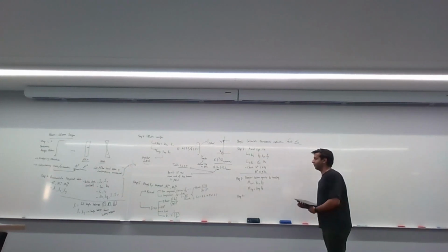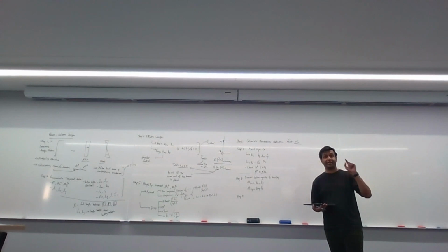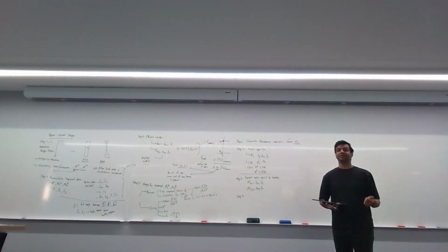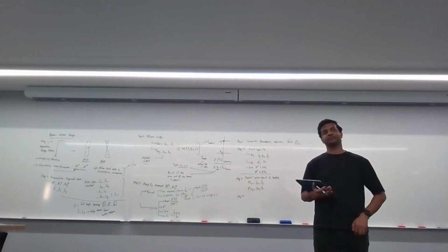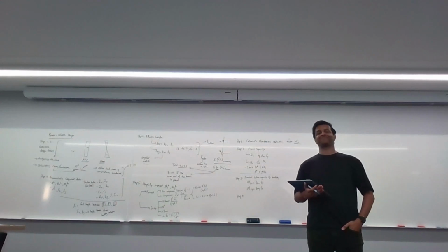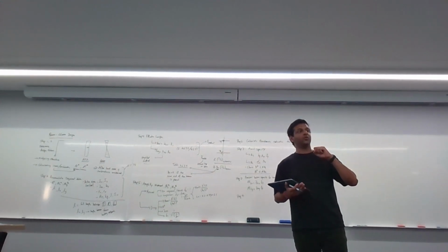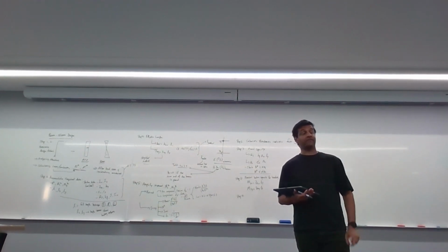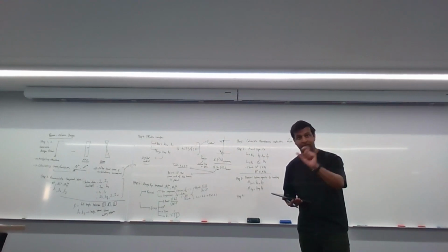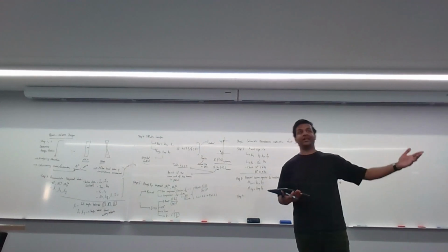So if it's completely laterally restrained, yes. But if it is not continuously laterally restrained, is there a way for you to check whether the code allows it to be treated as continuously laterally restrained? The L over Rx less than 80 plus 50. Very good. There's a clause in the code which says if the spacing between your lateral restraints is close enough, you might be able to say it's pretty much continuously laterally restrained.